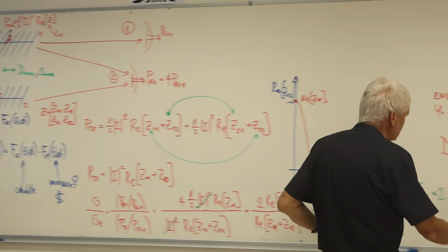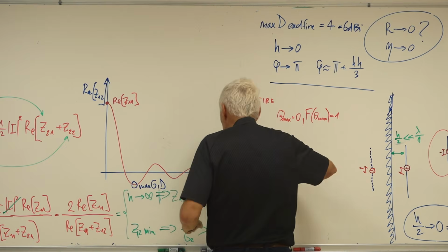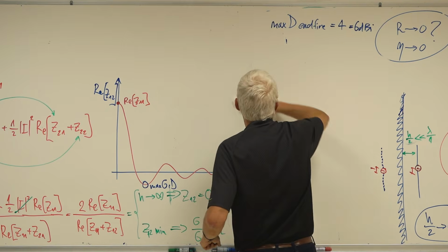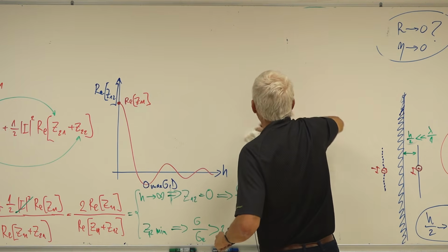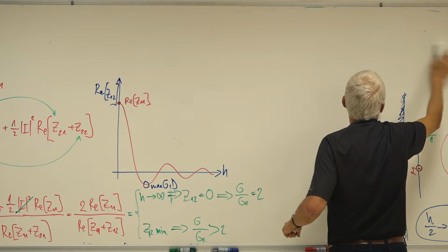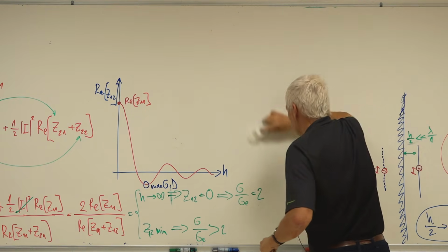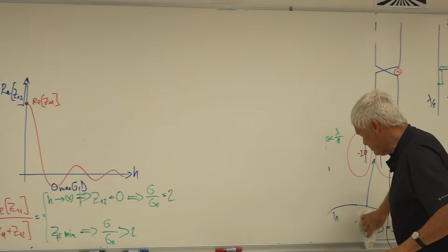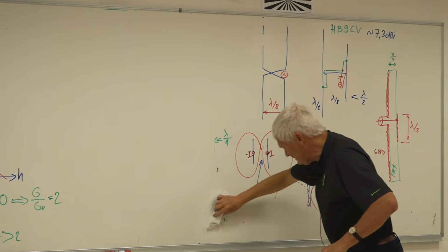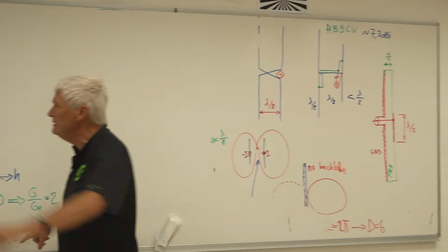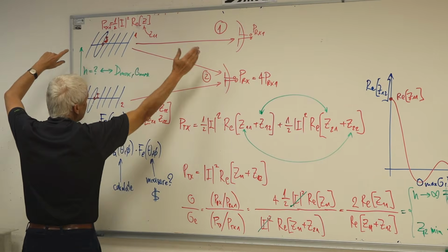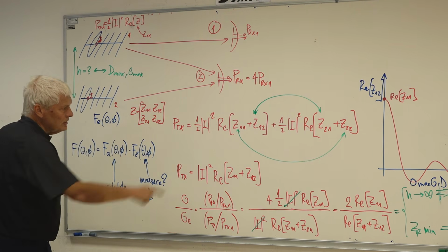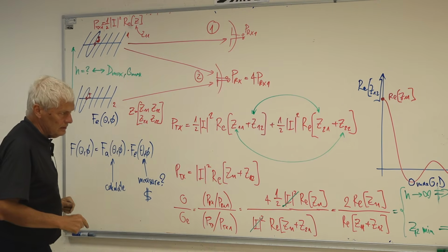You have an exercise to do it in the lab, and it gives you the same result. From this mutual impedance measurement, you can see how much gain or directivity you are going to obtain from building an array from two antennas. But even this measurement can be too large, too expensive. Even this measurement still requires open space to put your two antennas, nothing in front to minimize reflections, and measure the mutual impedance as a function of the spacing of the two antennas.